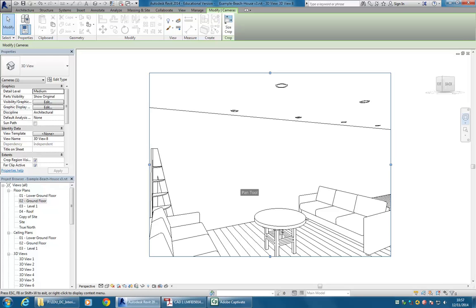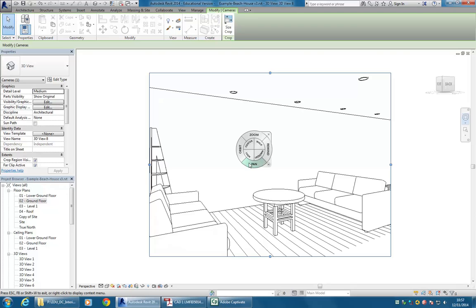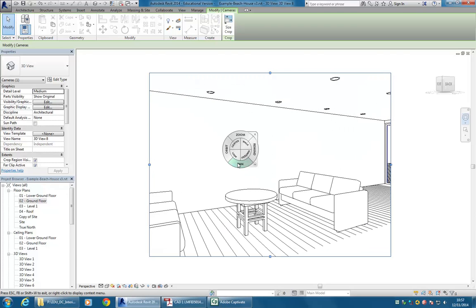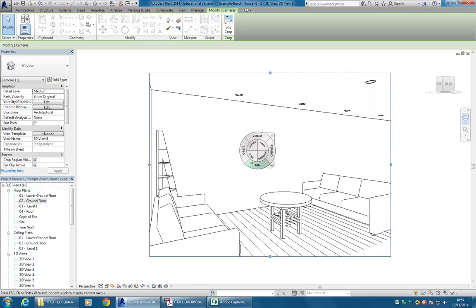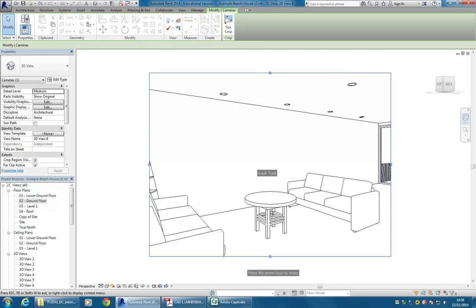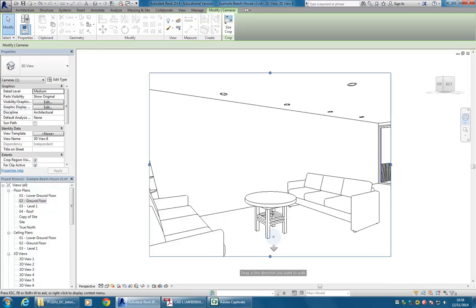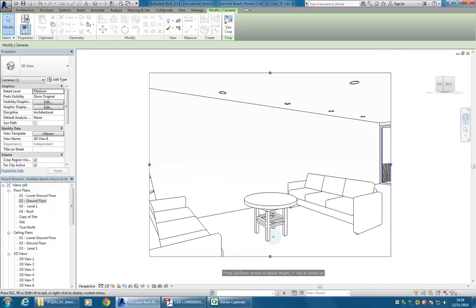But here I'm only going to use pan to bring the camera up and down. And then also across, I can use, sorry, that's about what I want. Look to change the angle that the camera is looking. And then walk, using that little dot there, you can bring the camera forwards or backwards. So just move it slowly at first to get used to that one.